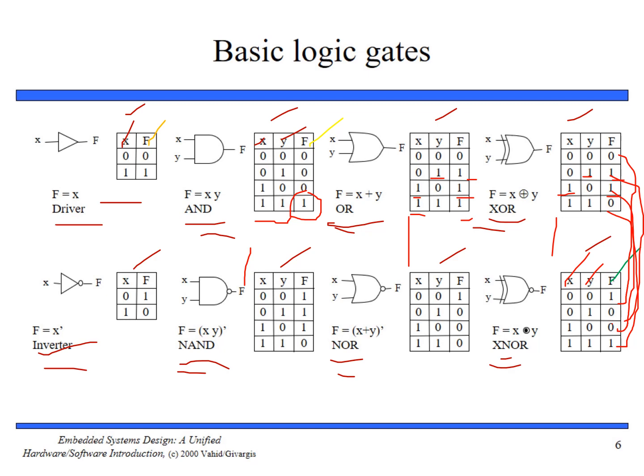But it turns out that PMOS transistors do not conduct 0 very well. Now listen carefully. PMOS transistors do not conduct zeros very well, though they do fine conducting ones. Likewise, NMOS transistors do not conduct 1 very well. They do fine conducting zeros. Hence, NAND or NOR gates prevail over AND or OR gates.